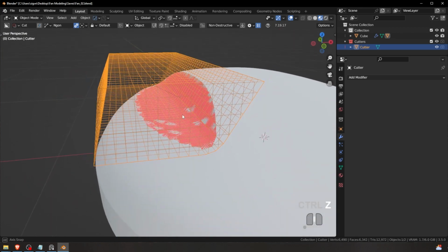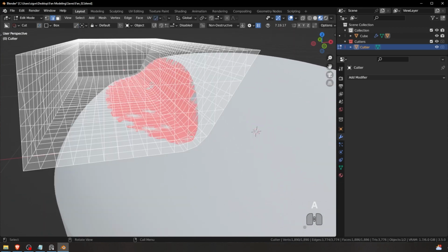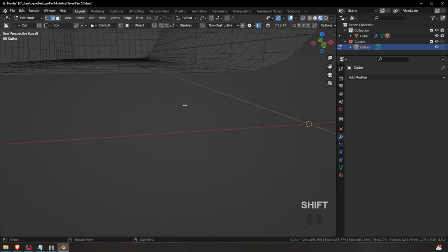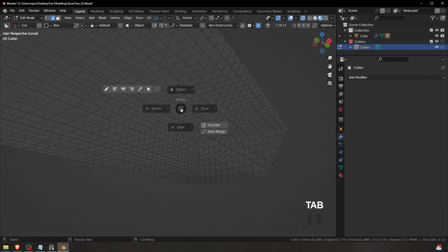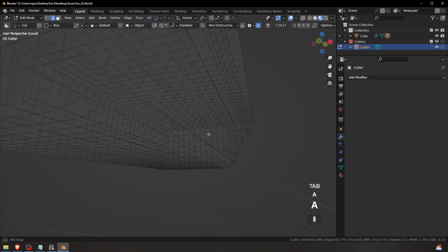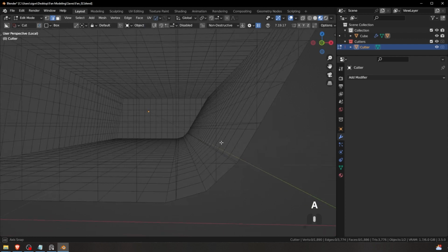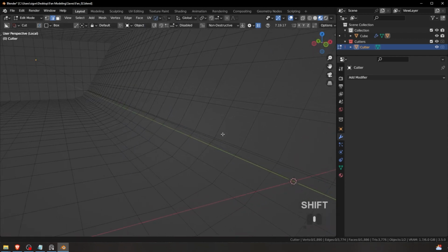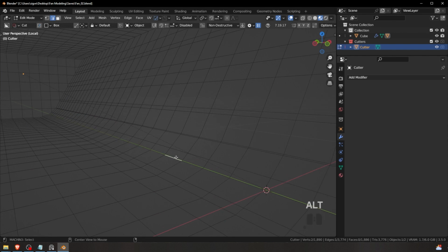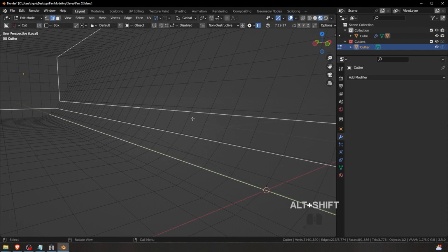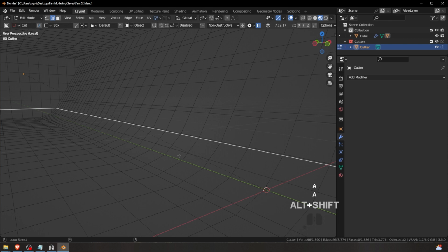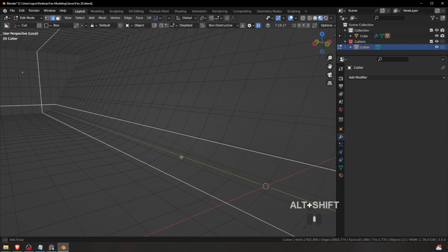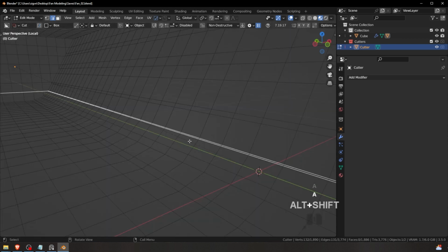But in our case, what happens is this. It creates a weird looking result, let me show you. We had the bevels right here running, right? And after we added this dice modifier, we got some uneven squares.